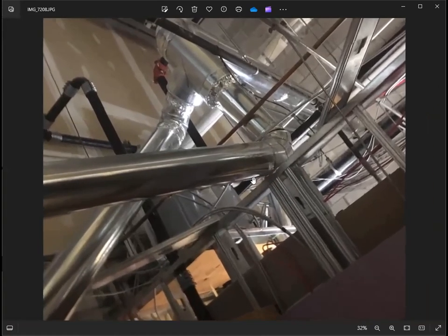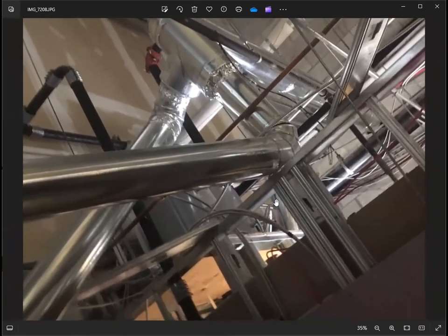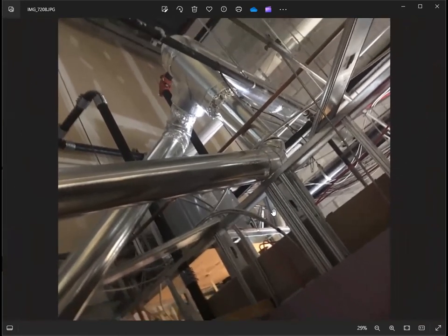And this is the main exhaust duct. This ductwork doesn't need to be insulated because you're throwing air from inside to outside the building. It's not a conditioned air duct. The only things you need to comply with in the drawing are the layout, the termination, and especially the support. As you can see here, this is only sitting on the existing wall frame stud.